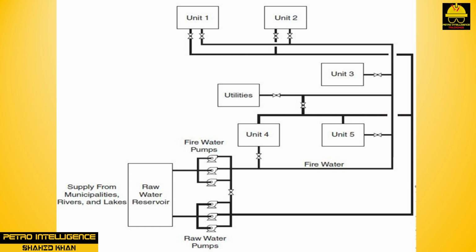Raw water is supplied to the units in the plant by pumps. All pumps can be remotely started from a utilities unit control service. Normally, 1 or 2 pumps are in operation to maintain 125 to 150 psig pressure on the RW system. All raw water lines are located above grade.